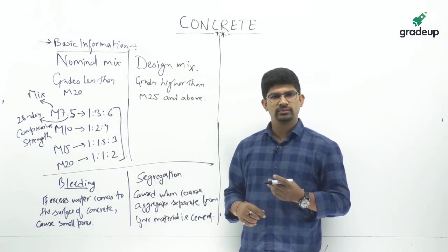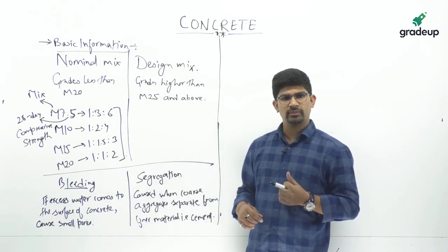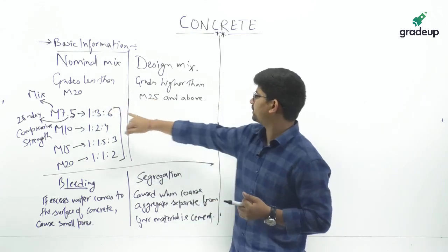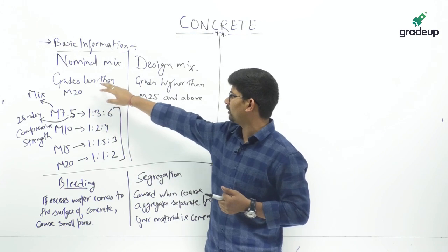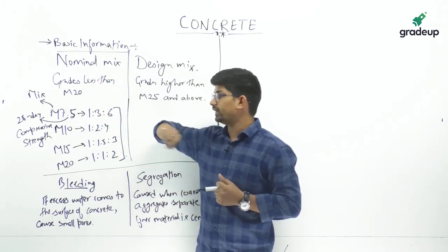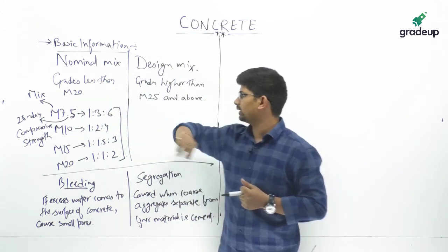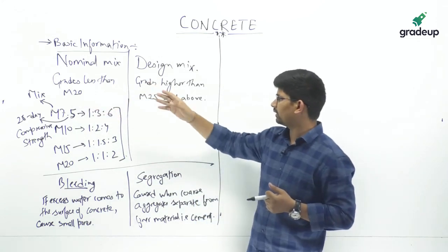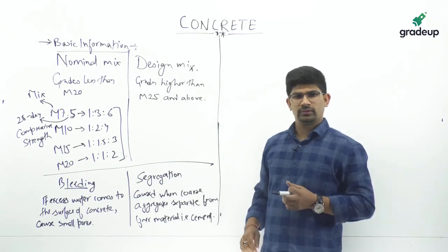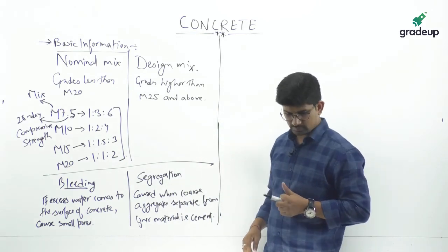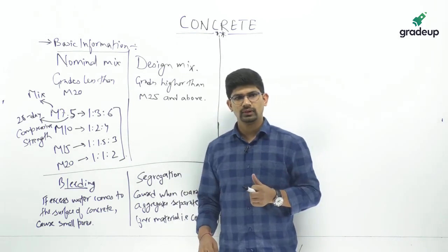Someone is asking about the ratios. See, these ratios are as per the IS codes. In IS 456 also you have read that for nominal mix, the maximum grade is M20, and grades higher than that are design mix.